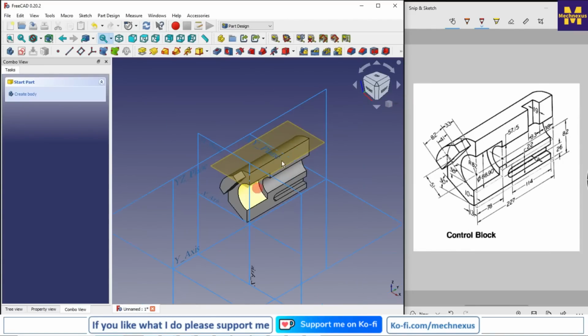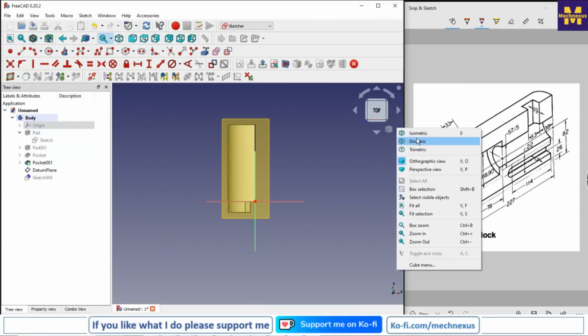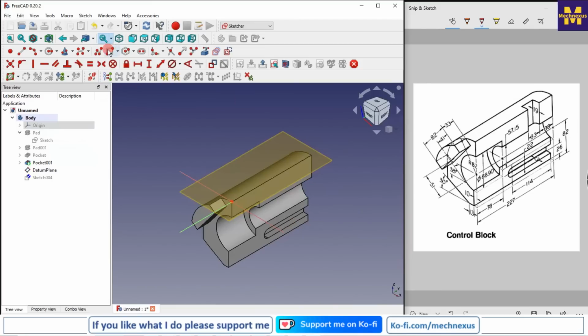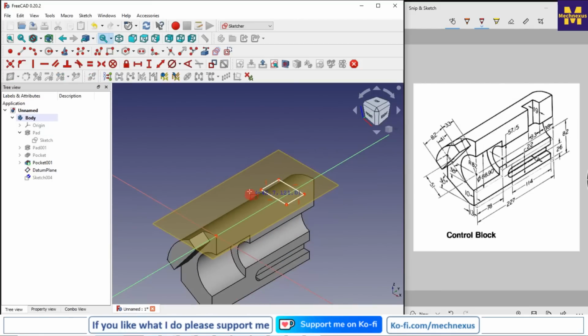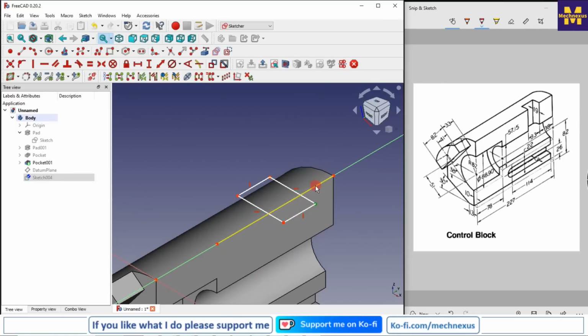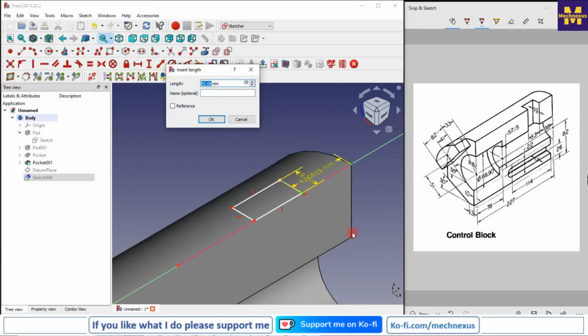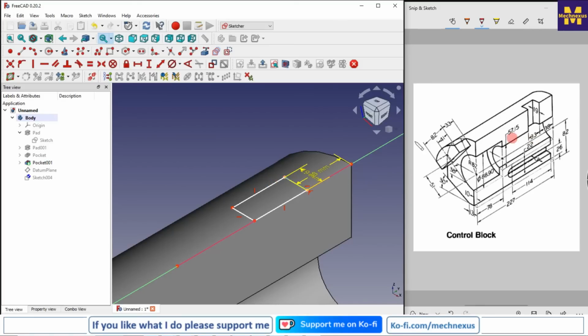And now we will create the sketch on it, so I will select my datum plane and say sketch, and I will go to my tree view and hide my origin plane. So in this case I will switch to the isometric and create a rectangle, and I will hide my datum plane, and now I will project my edge. So I will project this edge and I will select this point and this line and constrain it, and this is the 19 mm which we can see here, so I will give it 19. Position is 38 from the edge, so I will select this point and this point, and I will give 38, and this is the 33.